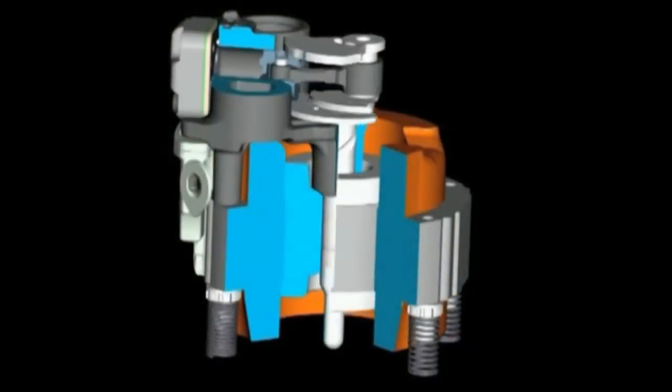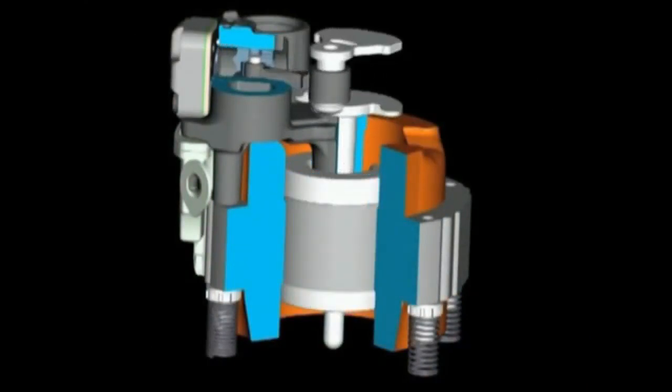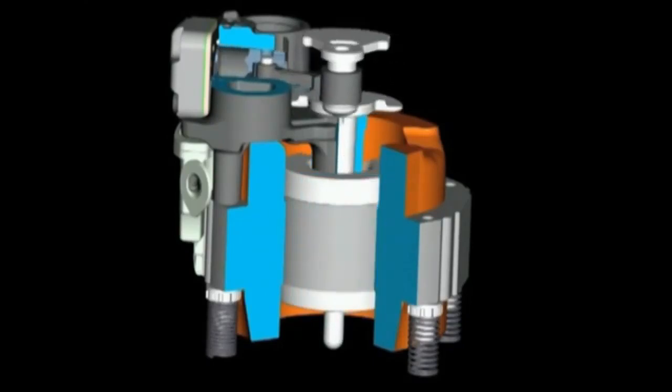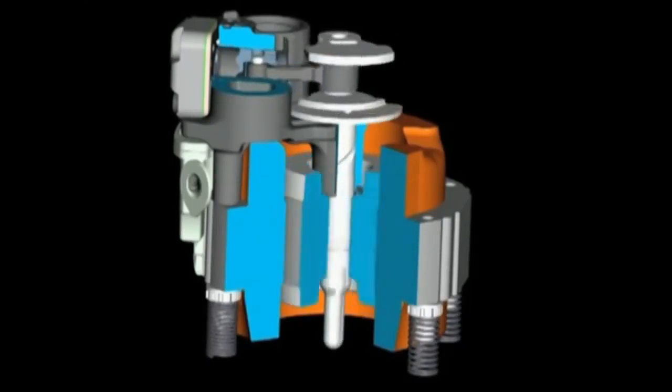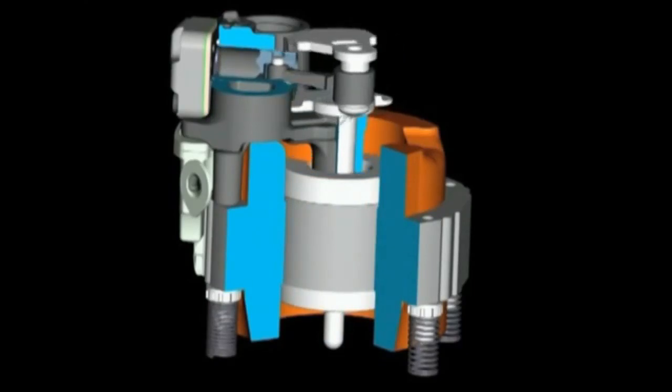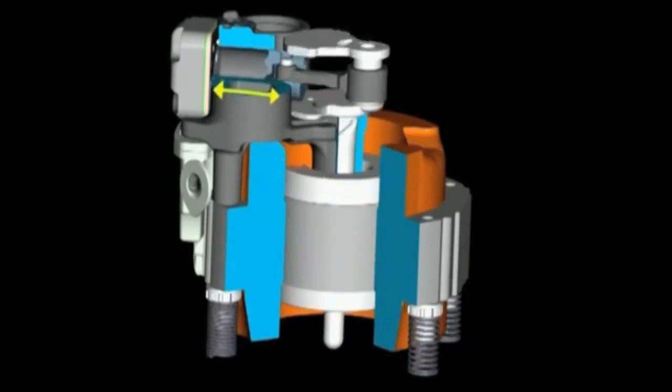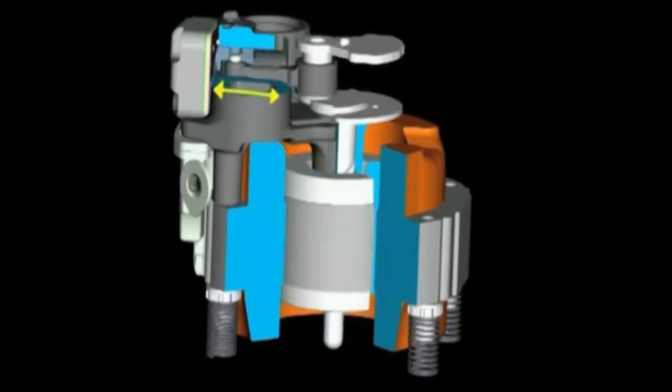The crankshaft is firmly connected to the rotor and transforms the rotational motion of the motor over the piston rod into strokes of the piston. These strokes make the piston in the cylinder move up and down, and thus the refrigerant is sucked in, compressed and discharged again.